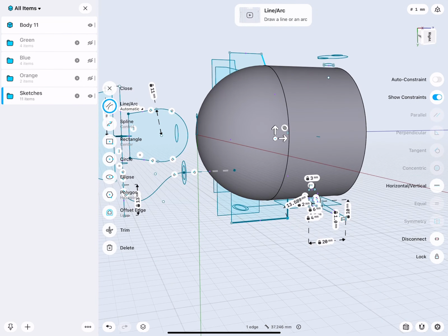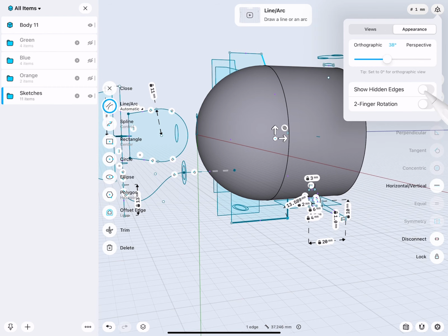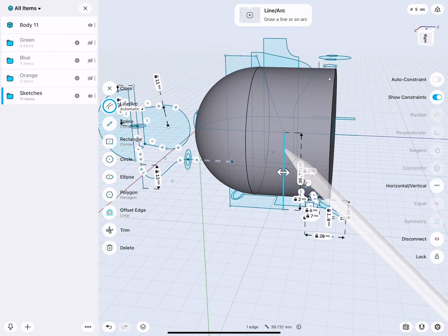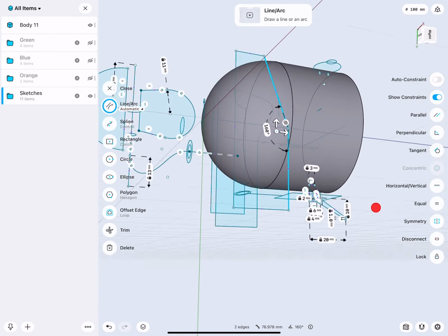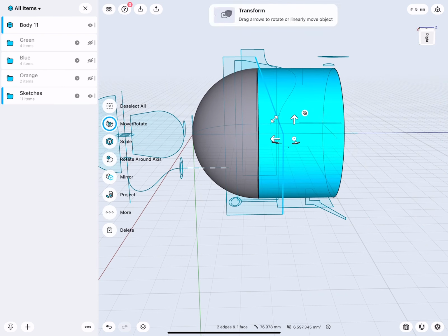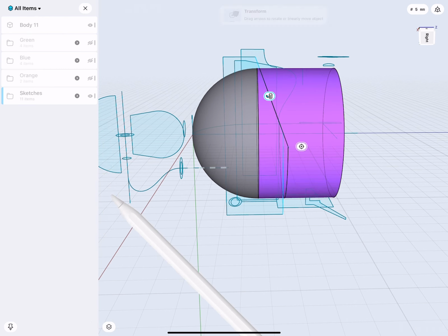Very nice. In 3D view, this is important. I select these two lines. This might actually also be good practice then to turn on this show edge, because you can see now I can select these edges through the body. Pretty nice. Select this face, and then on the left side, the toolbar now gives me the project command.